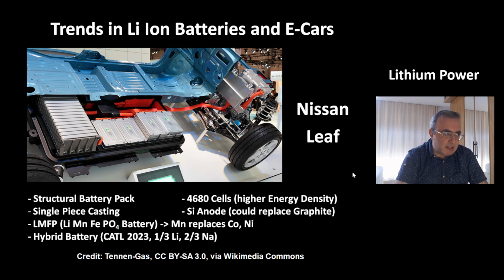And there's a big battery producer in China, that's CATL. They have plans to make hybrid batteries next year. The hybrid battery is 1/3 lithium, 2/3 sodium. Sodium-ion battery has a lower energy density, but it also has advantages, one of which is higher temperature resistance. And with increasing lithium prices, this hybrid battery becomes more and more interesting.